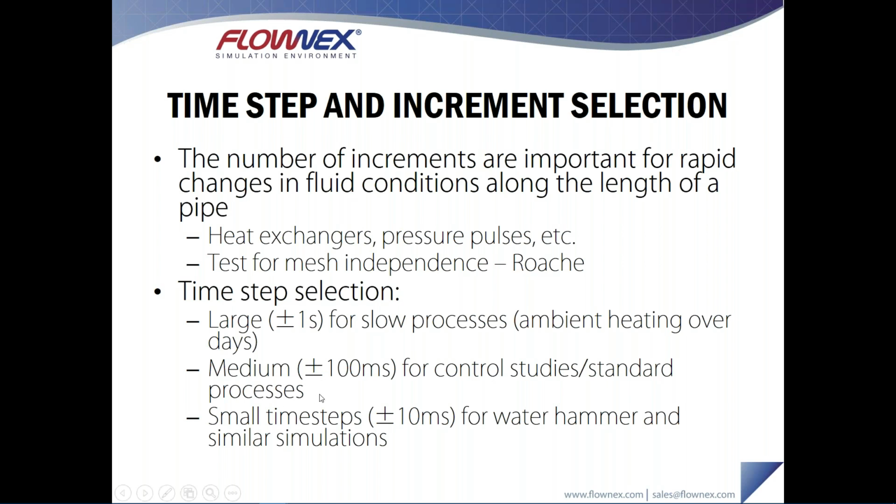For more standard processes, say you're doing an investigation of a pump trip, or perhaps there is a control study with the level in a tank or something like that, I'd recommend time steps of about 100 milliseconds. That's the default value in Flownex, and that should get you by most of the time. And then lastly, when you're considering studies like Waterhammer and other similar very fast transients, you're going to be looking at time steps in the order of about 10 milliseconds, sometimes even smaller than that. There are cases in short pipelines where 1 millisecond time steps are required.